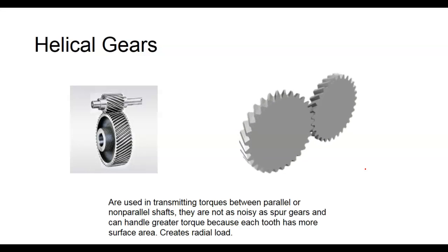So if we want it to be a torque multiplier, then your driver is going to be smaller than your driven. Anybody that's ridden a 15-speed bicycle understands it. You're shifting those gears. You've got gears on the front, which is your driver, and gears on the back, which is driven. If you watch that thing shift, if it moves toward the big one on the front, then your bike goes faster, but it's harder to do, right?